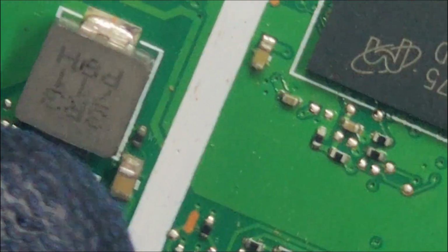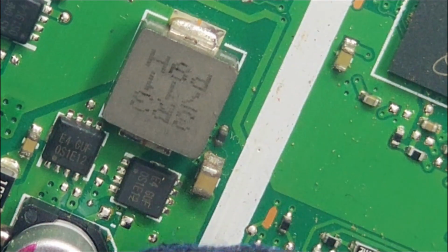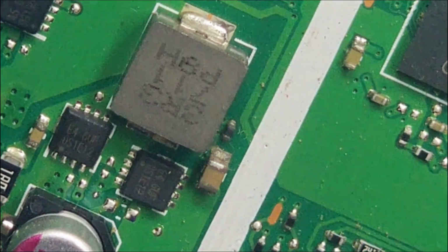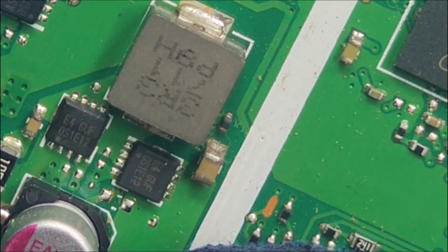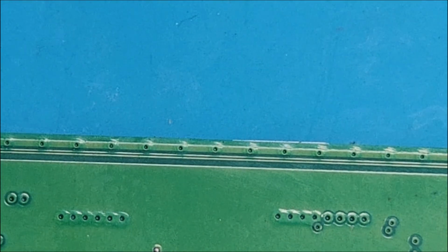Okay, yes, so we'll try to remove or isolate this current sense resistor from this place and check whether we have a short on the inductor here. If we have the short on that point after removing or isolating the current sense resistor, then the problem is with the lower MOSFET here. So that is connected straight to the ground. If the lower MOSFET got shorted, then it will connect the ground point to the inductor here. Okay, right, so let's see.